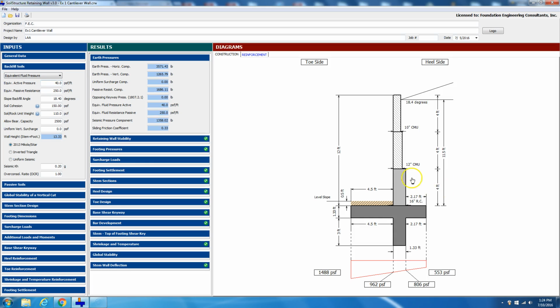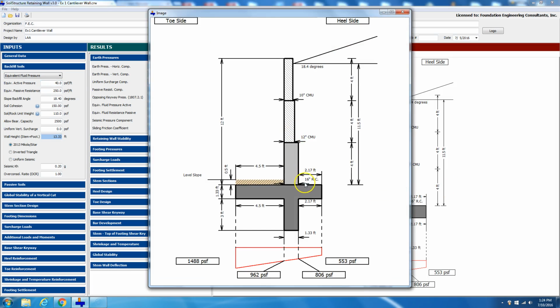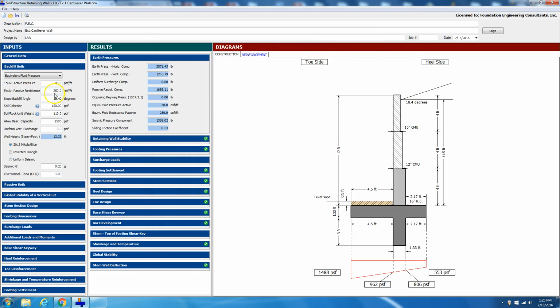So, for example, the back wall of the, let's zoom in here. If this wall is vertical, you can use the Rankine method, you can use the Coulomb method, and you can use equivalent fluid pressure. But when you start to have an inclined wall, where it's inclined into the hill or it's inclined away, so that means it's no longer 90 degrees, it's either less than 90 or greater than 90, then we cannot use Coulomb for that. He doesn't have a solution. But Mueller-Breslau did that. And so in this example, we're using equivalent fluid pressure, but just be aware of that.